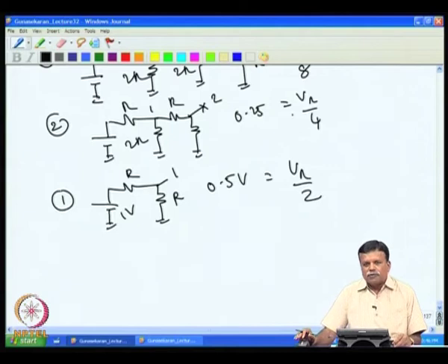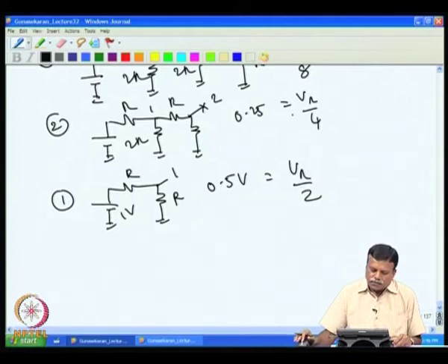So without having too many binary weighted resistors, we are able to get binary divided voltage using only two different resistors, R and 2R. Of course, the accuracy here also has to be maintained to the 2 power n bit, but nevertheless we have to fabricate only two different resistors rather than having n different resistors.